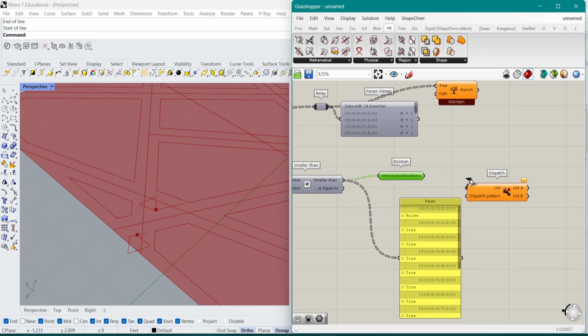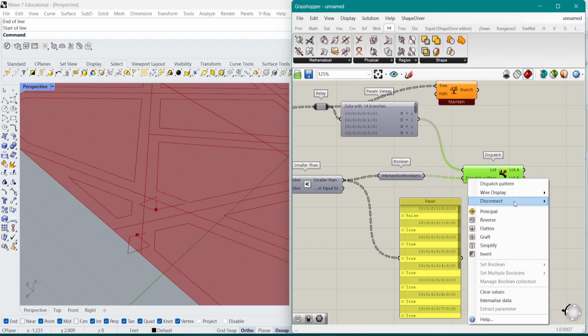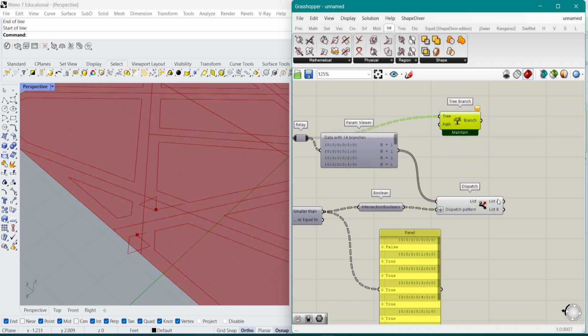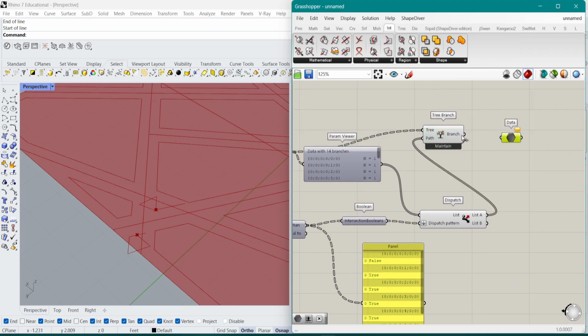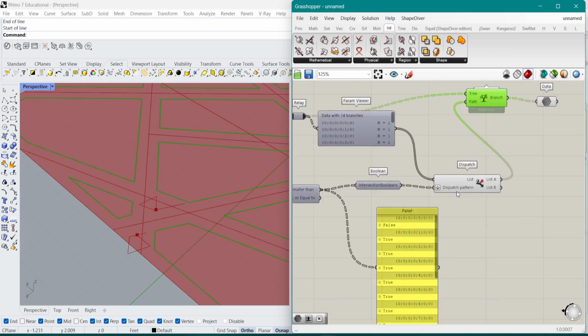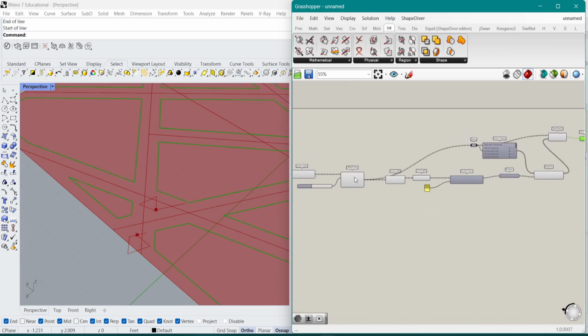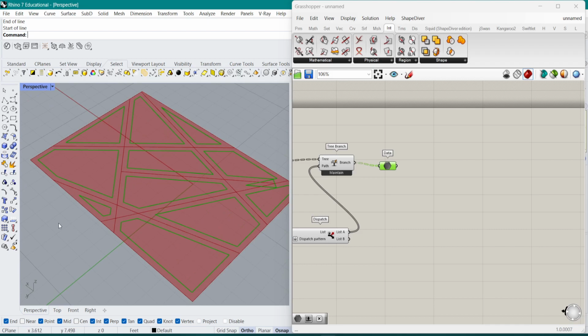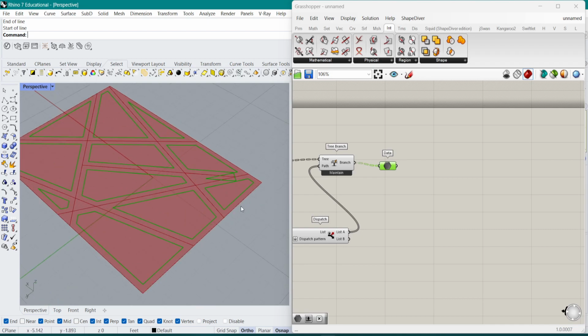Now, if I take this basic list of the tree that I want to remove those things from, and I use the intersecting booleans as the pattern, and I flatten this one, it gives me two lists here, one with 2 values and one with 12 values. If I use list A, I'm getting just the values that are not intersecting with the curve. So I have this as the main layer. If I make everything invisible, then you see, all right, cool. Now I only have the pieces which are not intersecting themselves. That's pretty cool. Now, obviously there is another problem here.